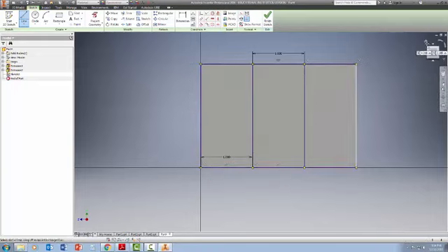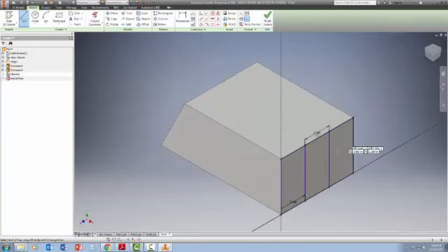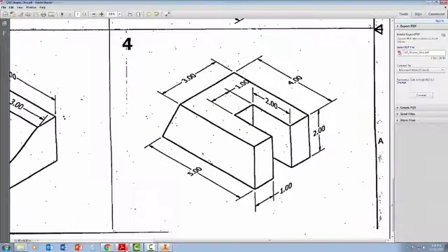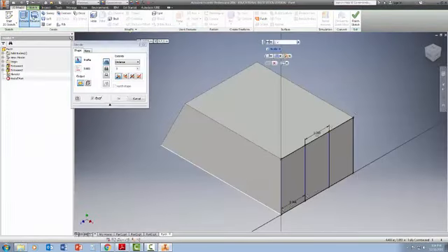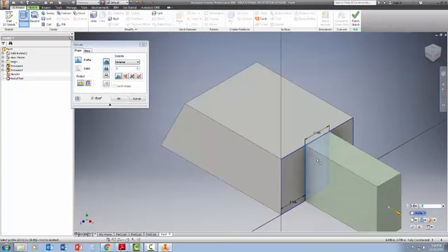So now what I can do is, if I just look at this from an angle, I've just made kind of 3 boxes here by really only drawing one full box, but boxing the whole thing in. Now I have to look back here and say, okay, how far does this come back in? It comes in 2 inches. Let's go back. I'm going to go 3D model, extrude. Okay, I want to do this 2 inches.